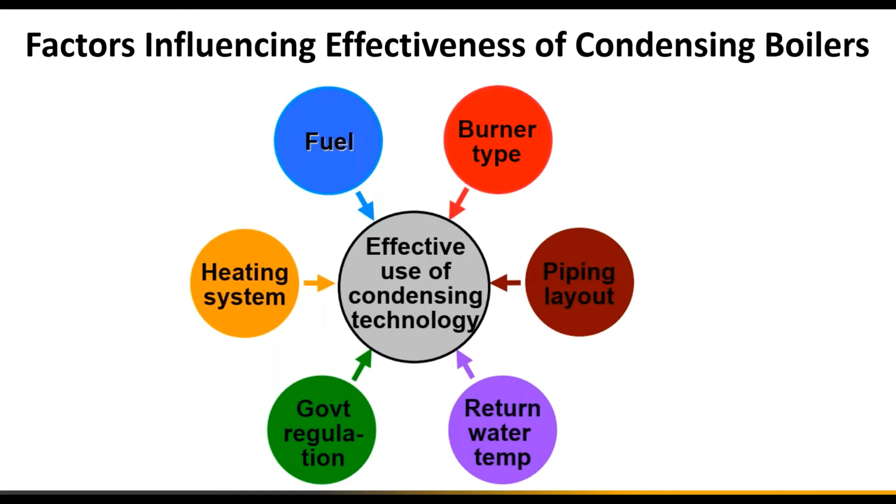Then towards the late 80s, they started really honing in on increasing overall efficiencies, lowering maximum supply temperature going out to the building for space heating and bringing back the return temperature. With the advent of condensing boilers in the early 90s, for new construction they came up with a new standard, dictating that for new applications the maximum supply temperature could not exceed 122 degrees, and the maximum return temperature on the coldest day could not be above 110 or 105 degrees.